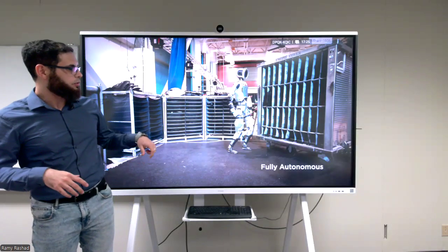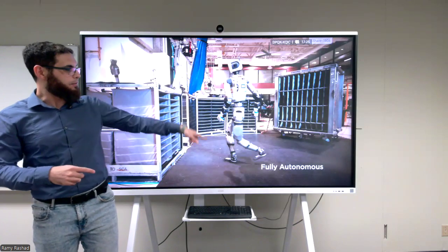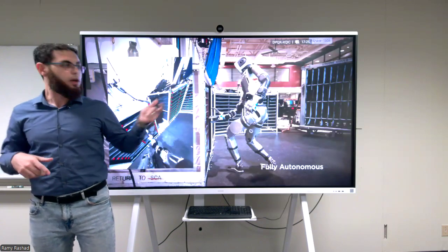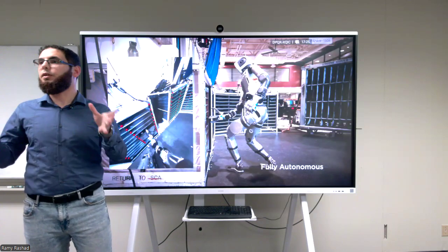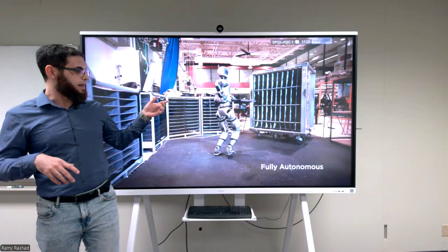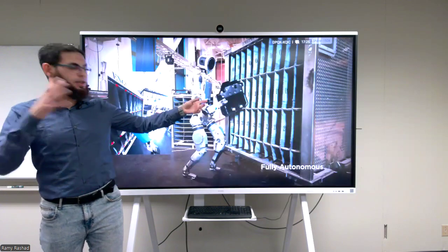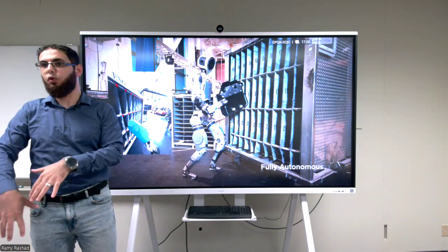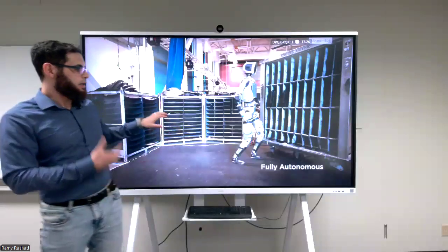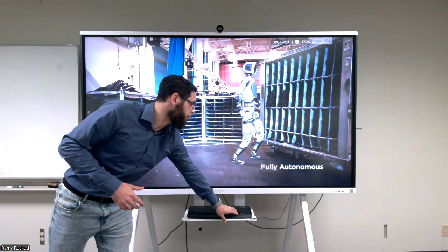The video is so slow. Sorry for that. So the right hand is one manipulator. The left hand is another manipulator. The right leg is a manipulator, and the left leg is a manipulator. So this is an example of a multiple branch floating base manipulator. This is very difficult also because it has contact on the ground. The body is not actuated at all. It's just moving by the reaction forces from the ground. So it also includes contact forces, which is something we didn't discuss at all.